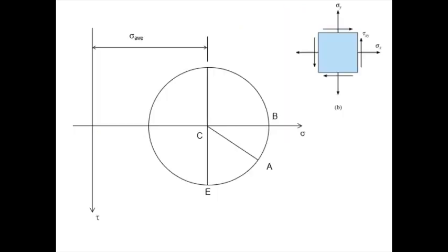Okay. So in other words, this is what you do. If when we look at this stress element here, sigma x is positive, sigma y is positive, and tau xy is a certain value, right? Now, if we try to determine from this, we will say that most probably the circle is going to be on the right of the vertical axis or shear stress axis. It's going to be on the right. How far right depends on sigma x, sigma y, and tau xy.